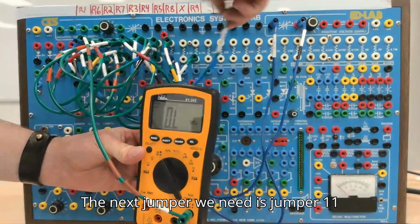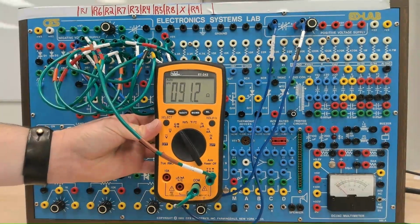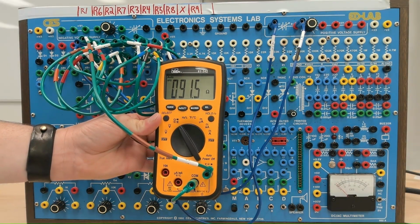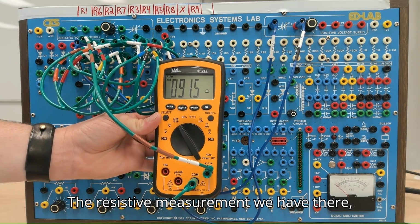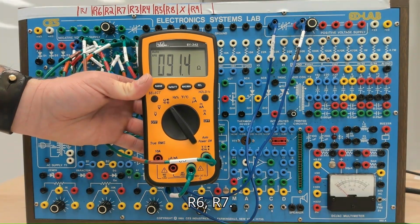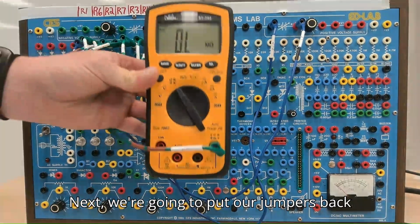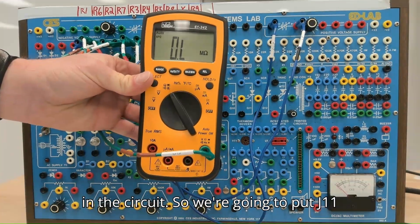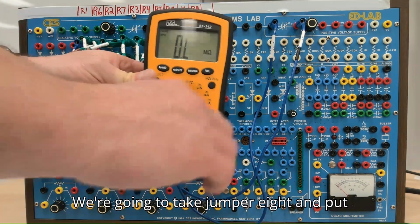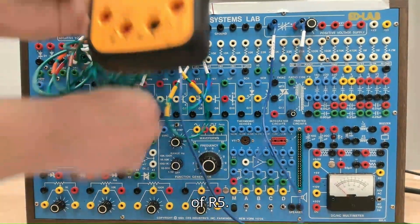The next jumper we need is jumper 11 off the top side of R9. The resistive measurement we have there, 91.5 ohms for R6, R7. Next, we're going to put our jumpers back in the circuit. So we're going to put J11 to the top side of R9. We're going to take jumper 8 and put it back to the bottom side of R5.